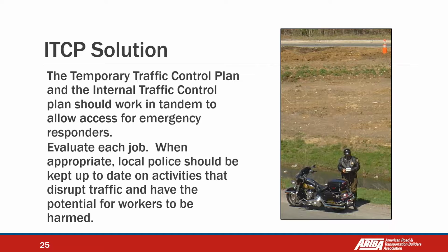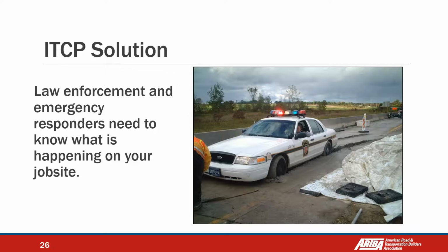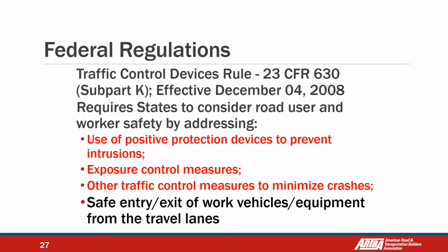So have clear communication with all the first responders that can help you if there is any accident, and be ready to guide them when they arrive to the work zone. If we don't provide clear indication, we could have this case. You can see this policeman arriving to the work zone, but he didn't know that we have fresh concrete in this area, and he is trapped because of this situation. So they need help, okay? They need guidance when they arrive.